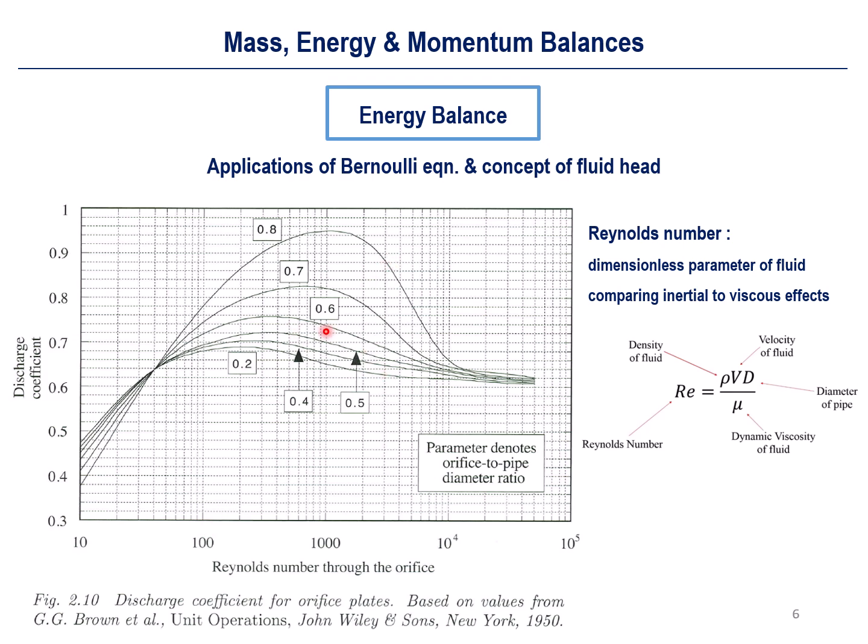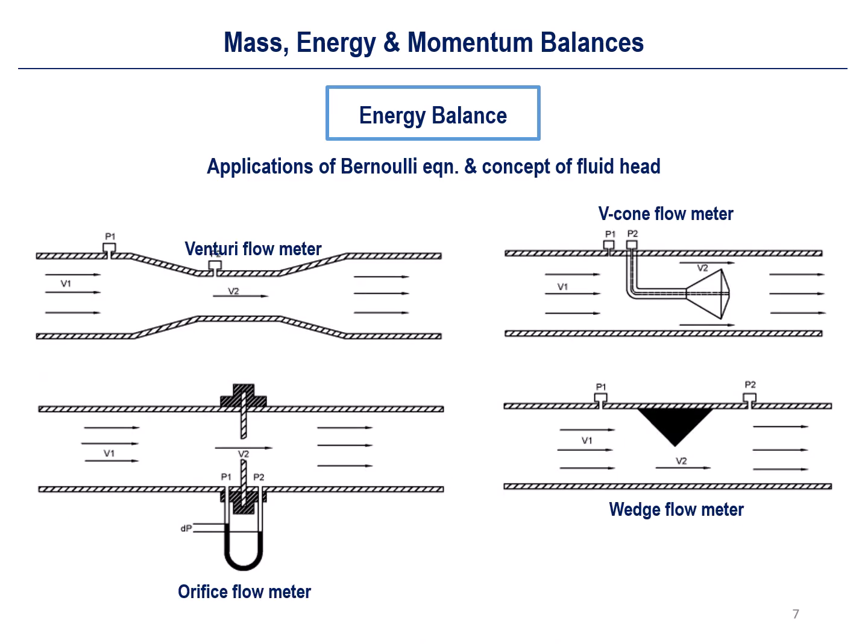If you do not have exact information about your manometer or your Reynolds number, you can reasonably infer from references or past data sets. So it is also important for the chemical engineer to track down these references and past data sets, because data to set this discharge coefficient and other related important parameters is not always available.